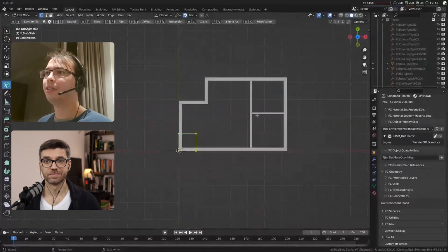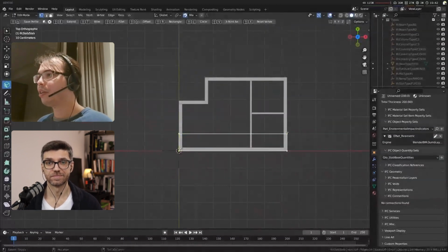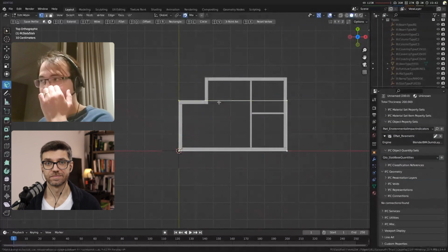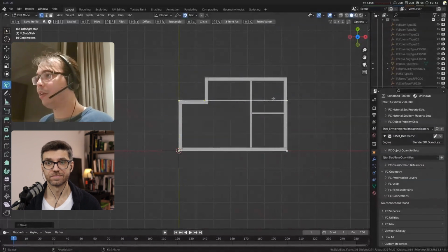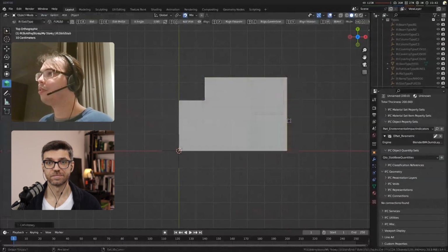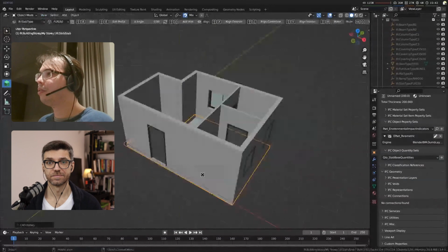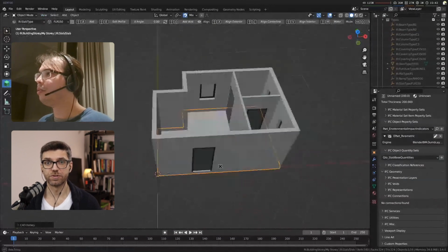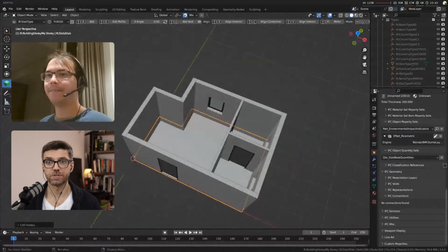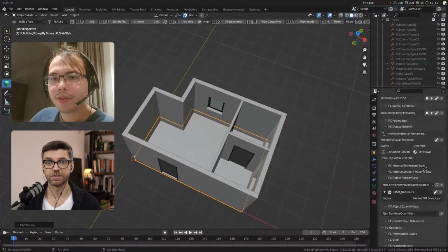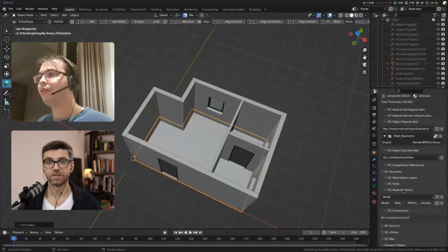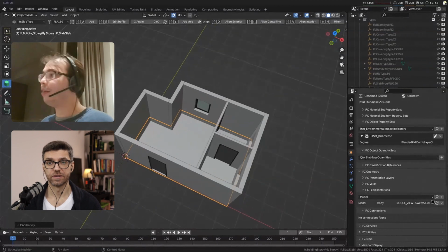Anyway, let's go and add in a slab or something. Let's create a new slab. Now the slab is a profile, so we're editing the profile of the slab. We'll put that here. This slab is also using all of BlenderBIM's editing capabilities. It's just a pure IFC slab. This is not a mesh, even though we're in Blender.